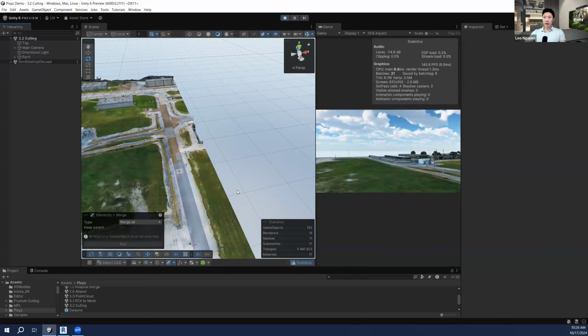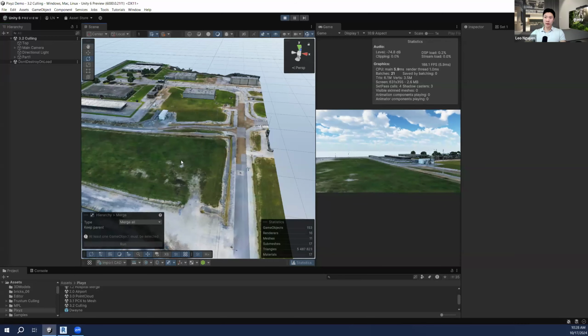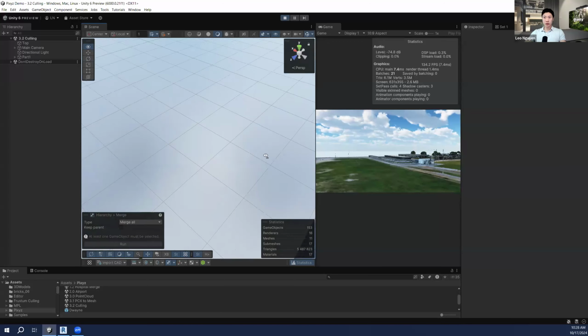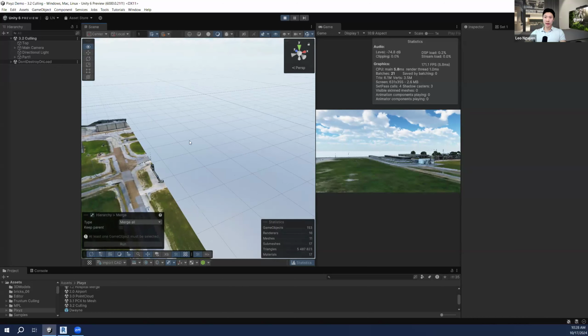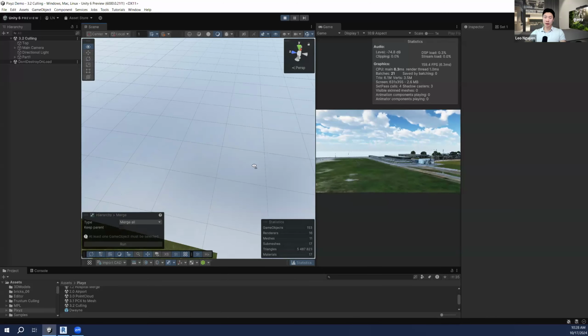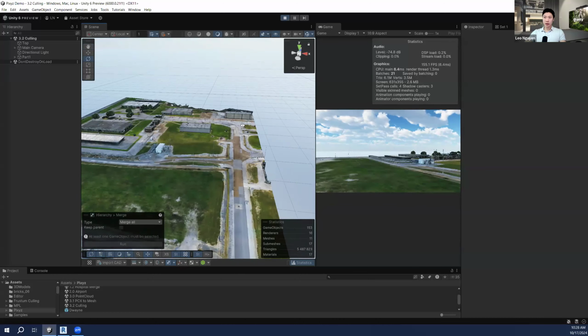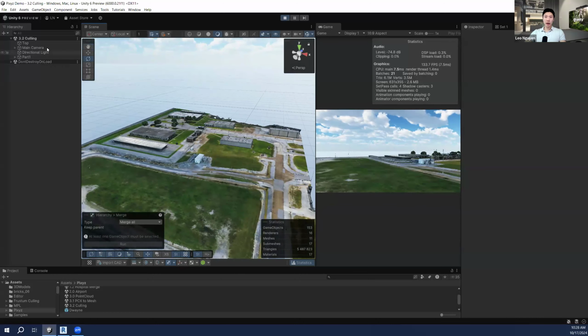So you can see here that when I click back into my view, there's only 5 million total triangles being rendered in the scene, because I'm able to use the frustum culling system, along with the way that Pixyz will split up the model, so that I could hide specific elements within the scene if I'm not looking at them.